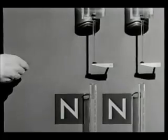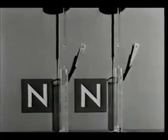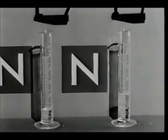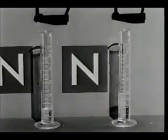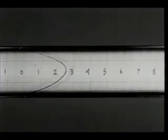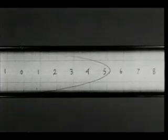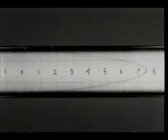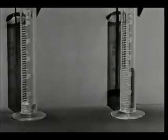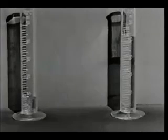In the steady laminar flow of incompressible Newtonian fluids through tubes, a single material constant, the coefficient of viscosity, governs the volume rate of flow and the velocity field. Here we get the familiar parabolic velocity profile. However, for more general fluids, the flow rate and the velocity field are governed by a viscosity function. For such a fluid, the velocity profile can be very different from parabolic.